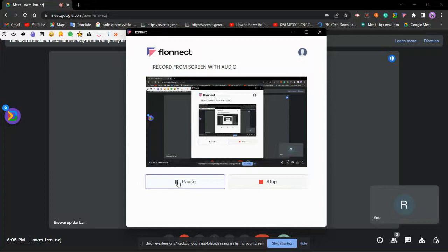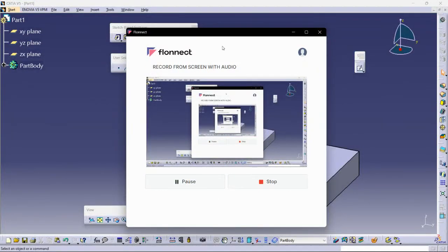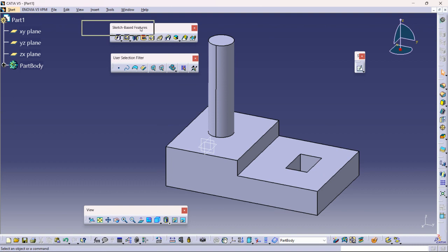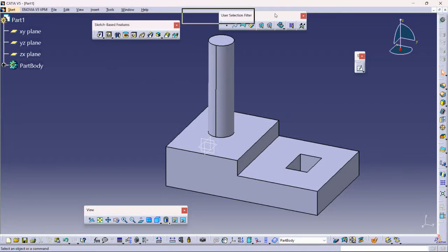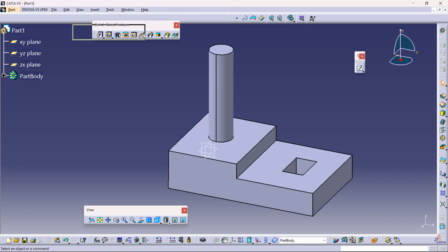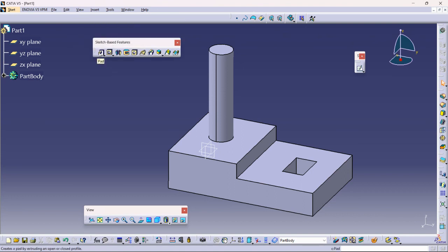Just before we see up to next, just reverse the direction. It is going in the wrong direction. If it is up to next, it will come up to here. This face has to stop the padding completely. Even if a small portion is outside this face, it won't work. Up to next won't be working. Then we have up to last. That means it will be extruding till the last portion.